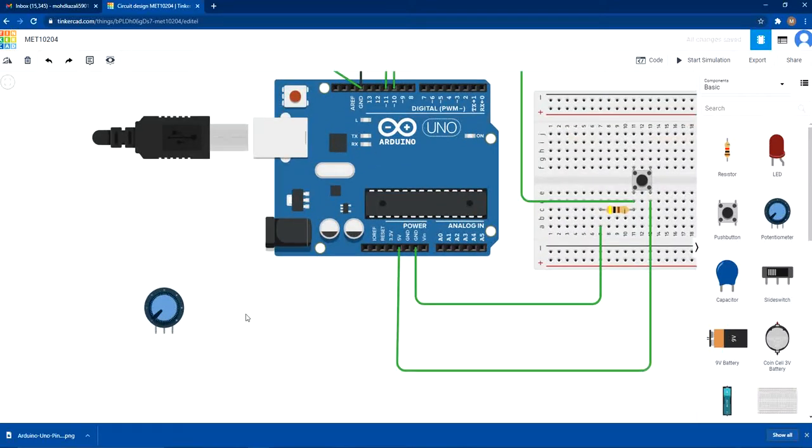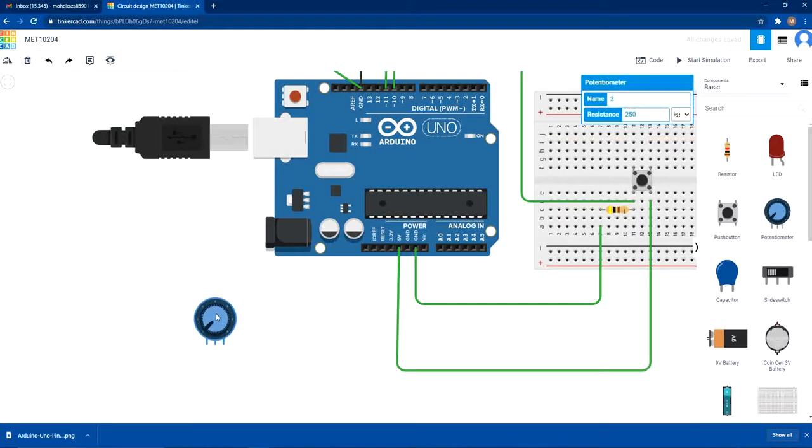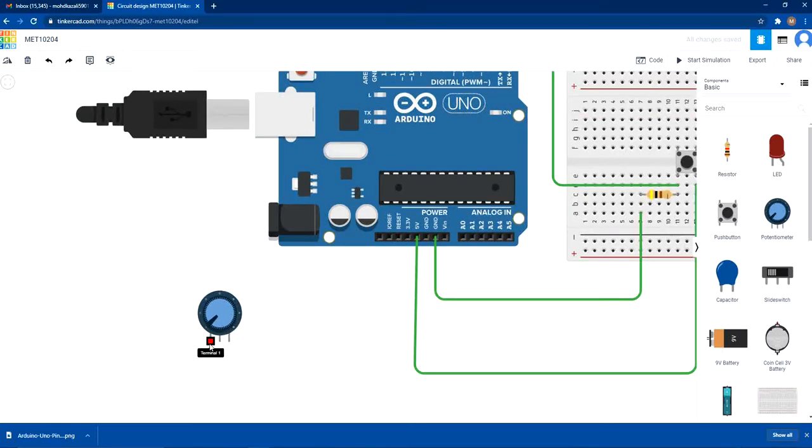So a potentiometer is basically just something like a variable resistor, but in a circular motion. Usually the potentiometer will have 3 pins, in which the center pin is the output voltage, and the left and the right sides are where we put the positive or negative.